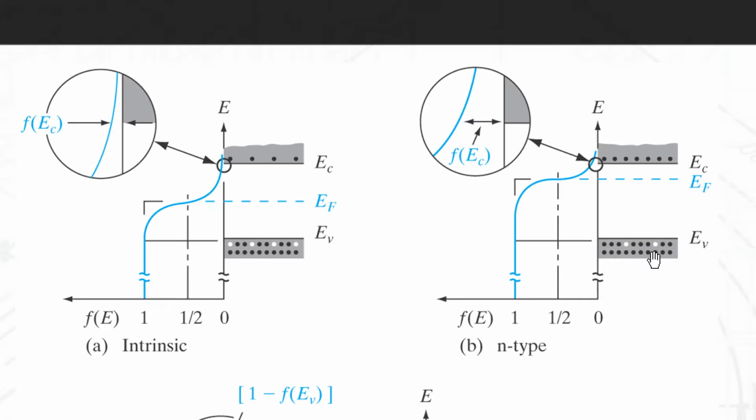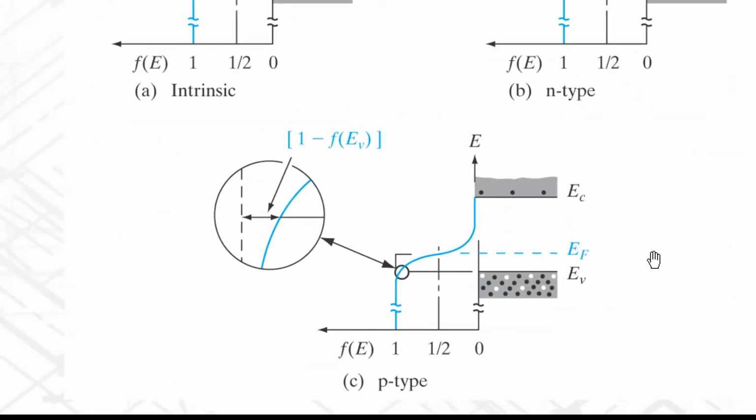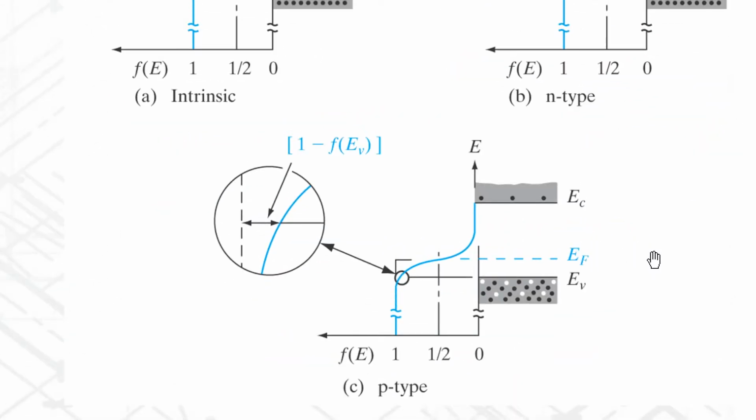Exactly. All right. So, yes. Can you dope something from like the 6th column so there's 2 extra electrons? Like if you combine 3 and 6? The question was, can you use something from column 6 to create a semiconductor? You have more than 1 donor per donor atom. You can create something, the 2,6 semiconductors where you combine a column 6 element with a column 2 element. Well, those combine to make an intrinsic semiconductor. If you combine them in equal ratios, then they combine to form an intrinsic, right?